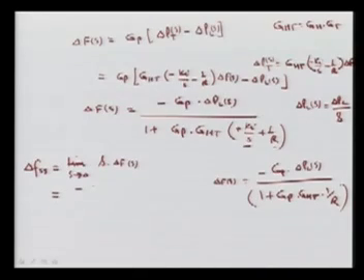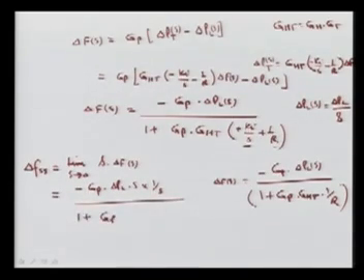Now you can put this value here. It is nothing but minus Gp, and this value is nothing but your change in PL. You are multiplying by S as this term, and here it is 1 over S. Now here we have 1 plus Gp, GST, and here Ki over S plus 1 upon R. Now we have to put S tends to 0. So if you are putting it here, you can see this cancels with this. Now what will happen if you put S tends to 0? Here we are getting Kp, 1 over 1 plus TpS, means only Kp we are getting. This is a constant, here it is 1.